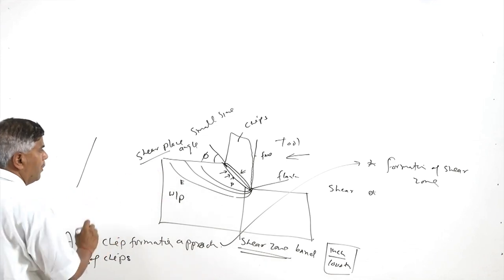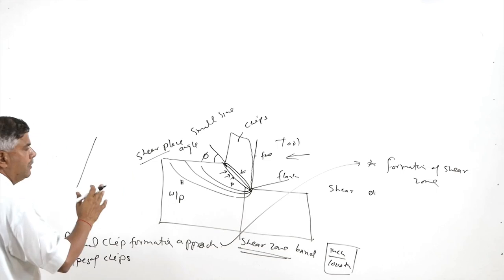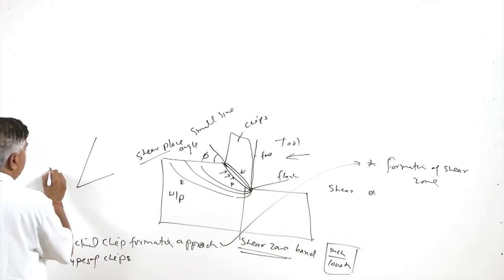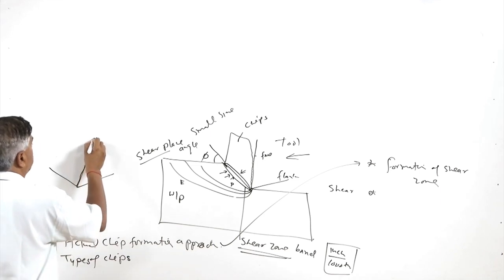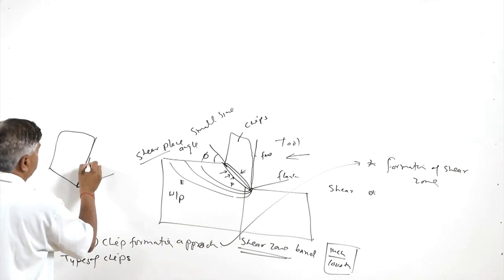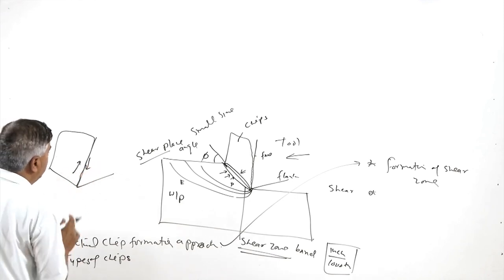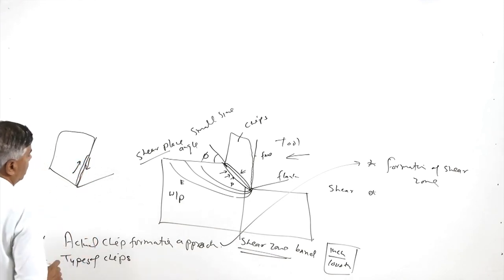So, this is the shear which is facilitating the removal of the material in the form of chip from the workpiece, while the material after getting removed under pressure passes over the face of the tool like this. Since there is friction during the movement of the chips over the face of the tool under pressure, some kind of deformation is also observed along this zone.